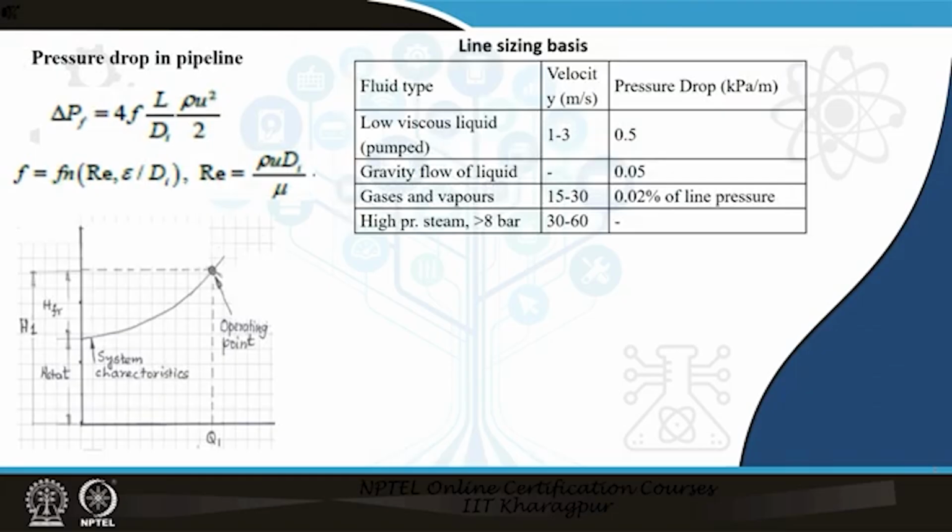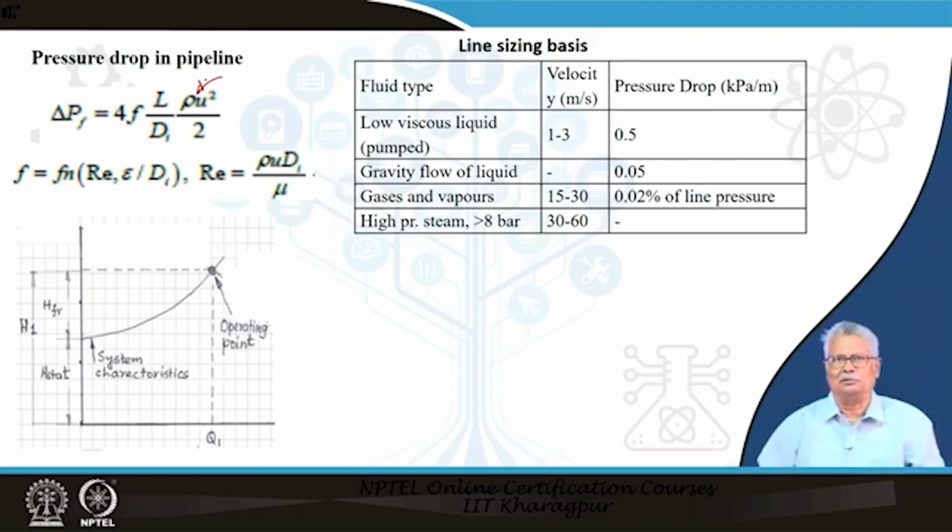Regarding piping, what we have said is we know basically how to estimate the pressure drop in a pipe whenever there is a flow which leads to a velocity of u. That is, the velocity u multiplied by the cross section, pi by 4 into d square, gives you the flow rate. And part of it is done already, because we also know how to use the Moody's friction factor chart, whatever you may call it, and you can find out.